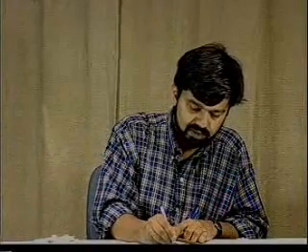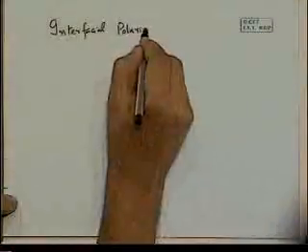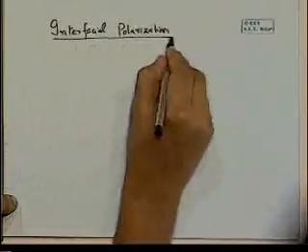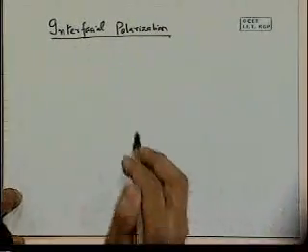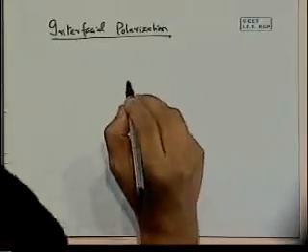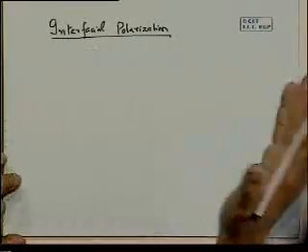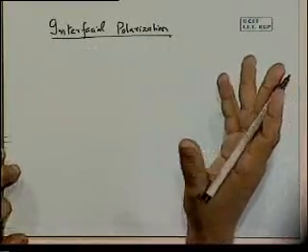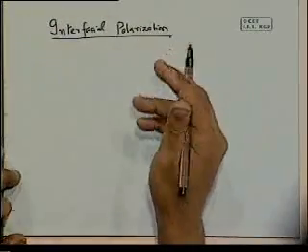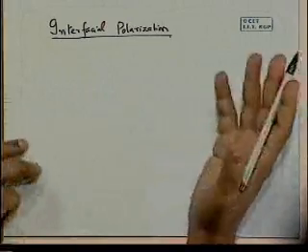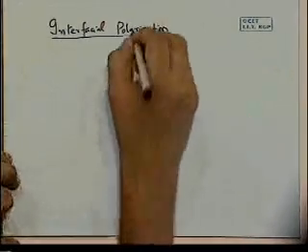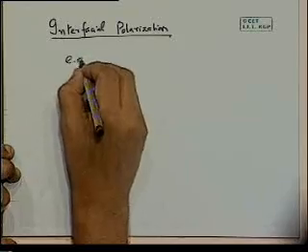We come to the last mechanism of polarization, namely interfacial polarization. Here the basic idea is that the charges accumulate at some interface. For various reasons, they will build up at a certain interface, they can't move further, and then when they are building up there, they add to the dipole moment. Some interface where they can't cross, they get stuck there, and as a result they build up higher polarization. Take an example of that.